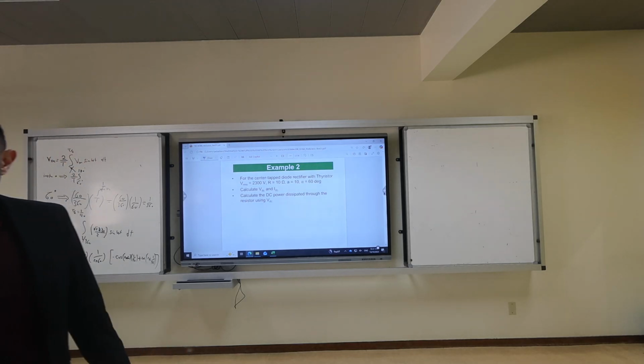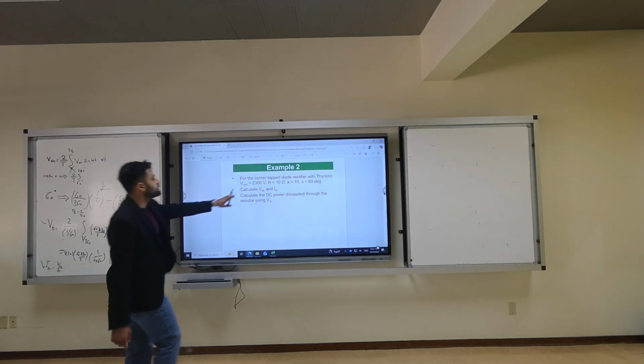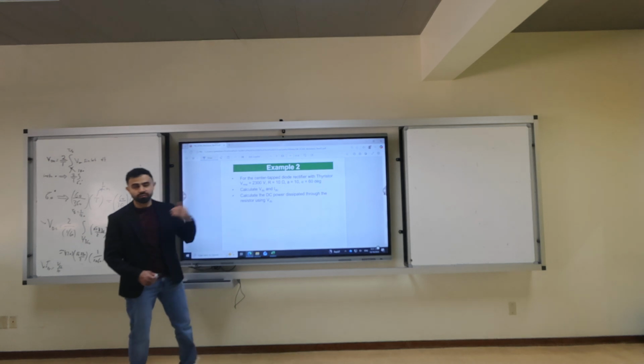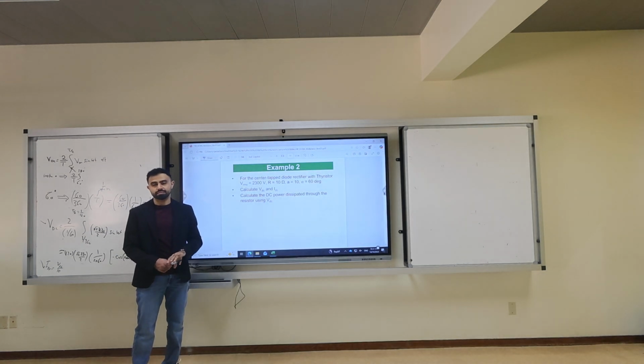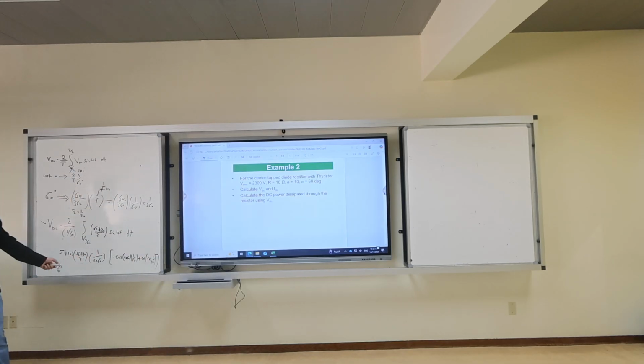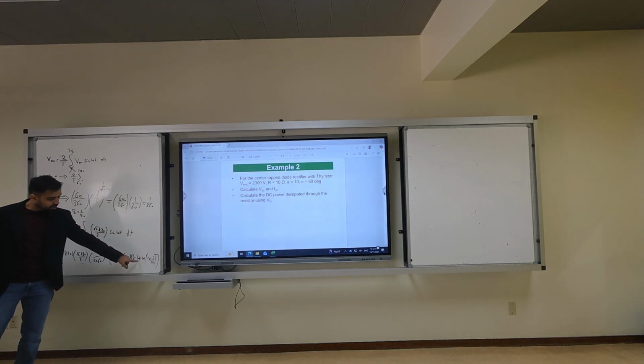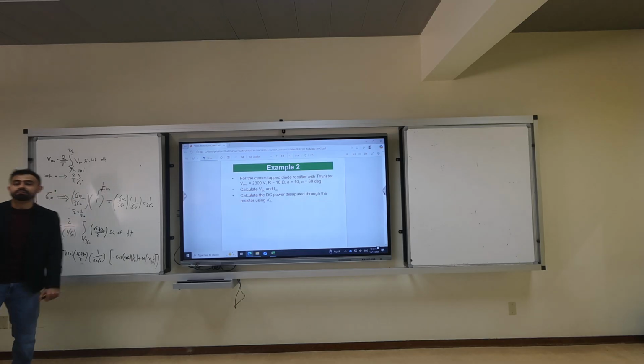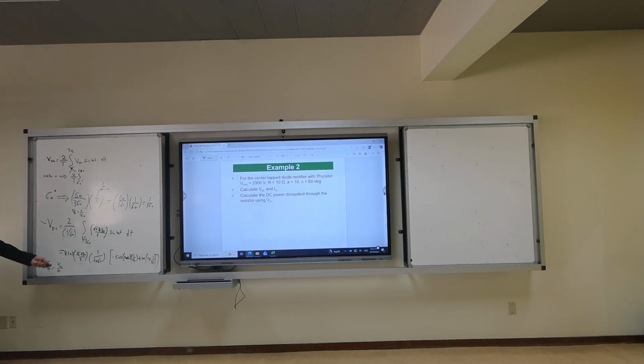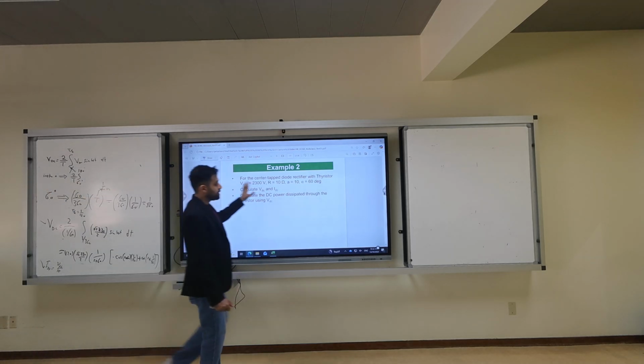Okay? Power DC is VDC times IDC, or VDC square over R, or I square DC times R. Can you do this by yourself? Not gonna ask you in the test, but try to do it. Okay? What's the integration of sine? Minus cosine. So it's minus cosine omega t, minus plus cosine omega the other t. And whoever is doing it, that will be awesome. Clear? So enough about that.